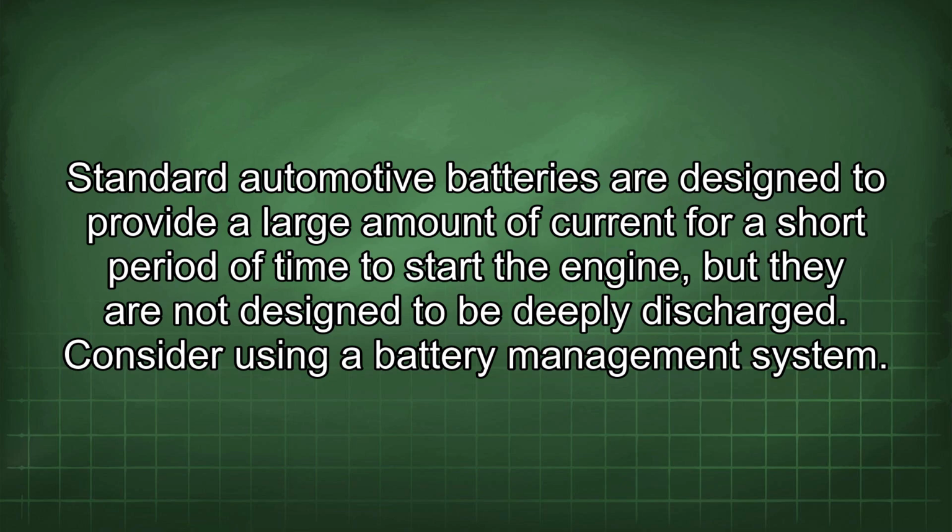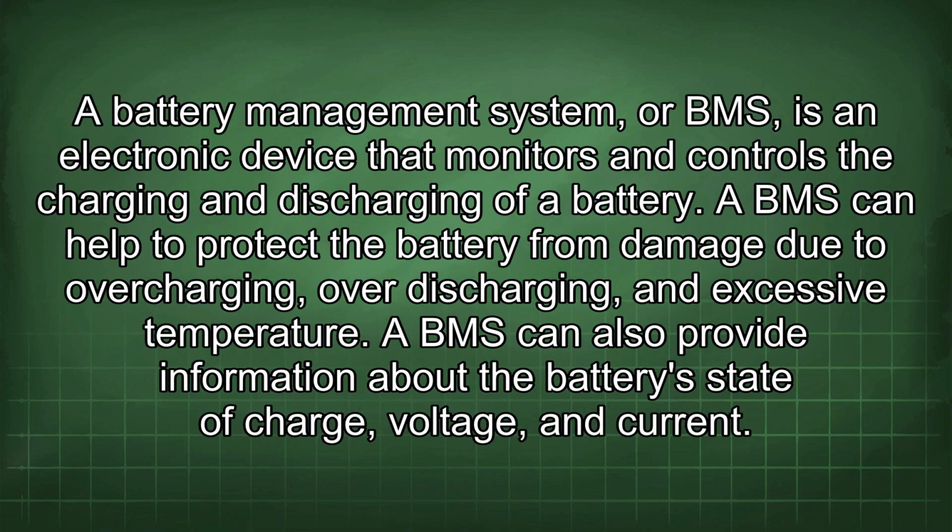Consider using a battery management system. A battery management system, or BMS, is an electronic device that monitors and controls the charging and discharging of a battery. A BMS can help to protect the battery from damage due to overcharging, over-discharging, and excessive temperature. A BMS can also provide information about the battery's state of charge, voltage, and current.